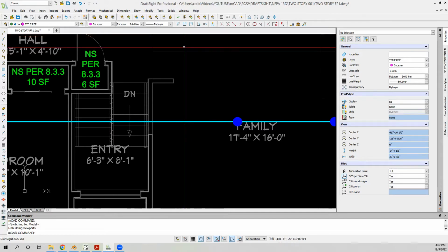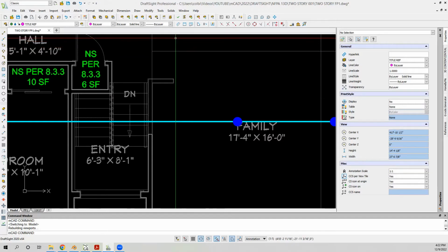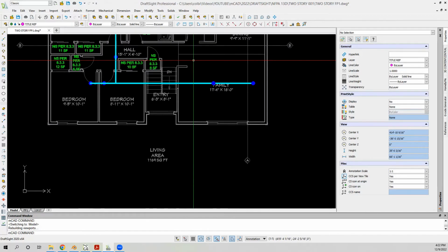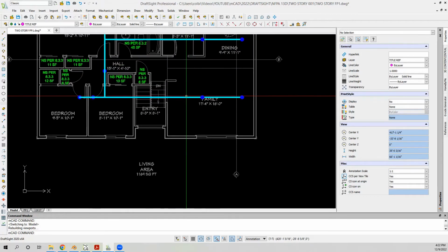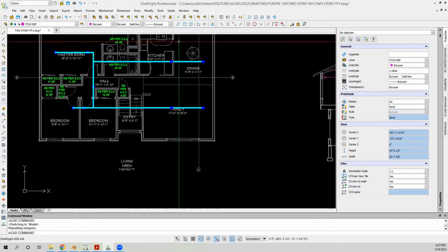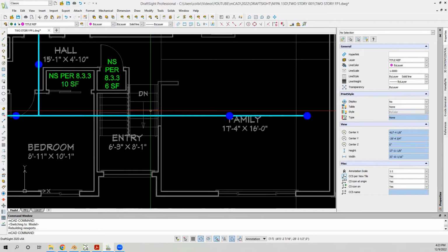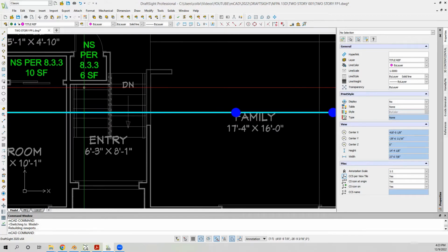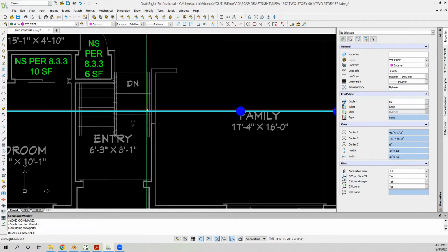The supply to this house, I happen to know that it's 1.25 PVC, so we could increase our riser size from the first to the second floor to 1.25 if we had to, if it was real low pressure. But moving on with layout, let's get out of the weeds here.